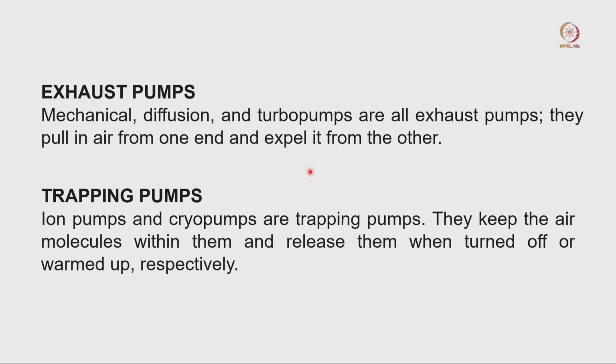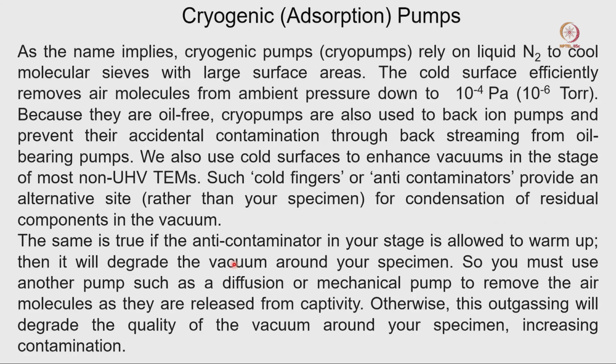Okay. Now, I already mentioned the exhaust pump and the trapping pump. Now, we will discuss one more pump, called the cryogenic pump. What is the cryogenic pump? As the name implies, cryopumps rely on liquid nitrogen to cool a large surface area. This cold surface efficiently removes air molecules as well as a small amount of water molecules, from ambient pressure down to 10 to the power minus 4 Pascal.